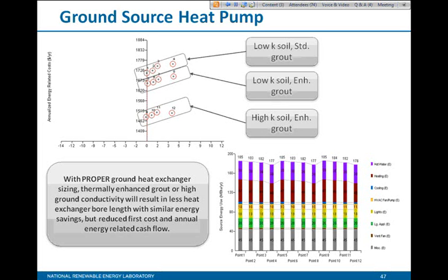Is there any plan to improve the EnergyPlus simulation for ground source heat pumps? Yes, we have filed two tickets with the EnergyPlus team. One is regarding proper desuperheater sizing, and the other is regarding the horizontal trench model. Thank you for mentioning this two-stage modeling; we will also report it to the EnergyPlus team.